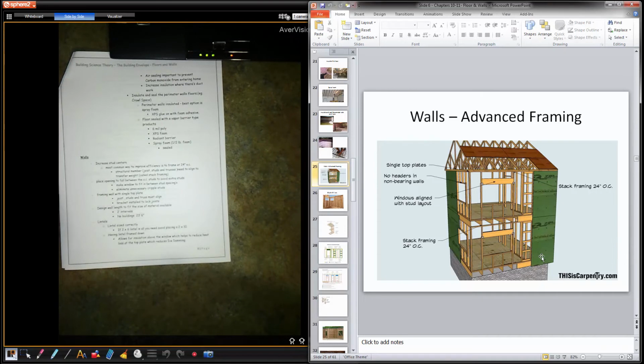Structural members, joists, studs, and trusses need to align. So if you're going to do that, you can see the alignment. Studs right over top of floor joist, right? So all the way up from the ground. So joist, stud on top of joist, joist on top of stud, stud on top of joist, truss on top of stud. So all your members have to line up. So you got to make sure you do your layout from the same corner for all your components.